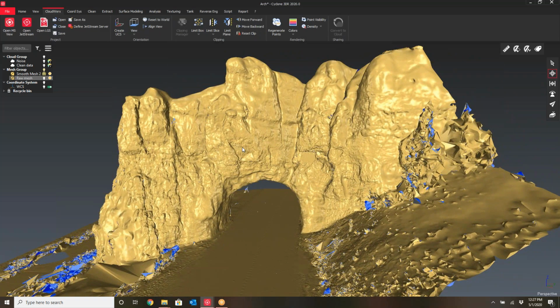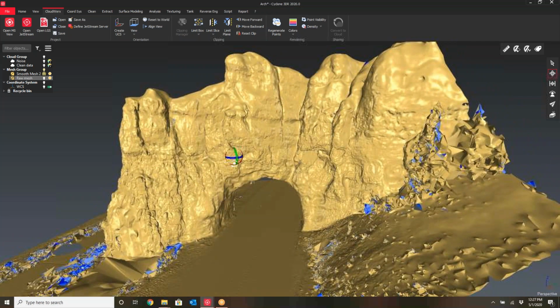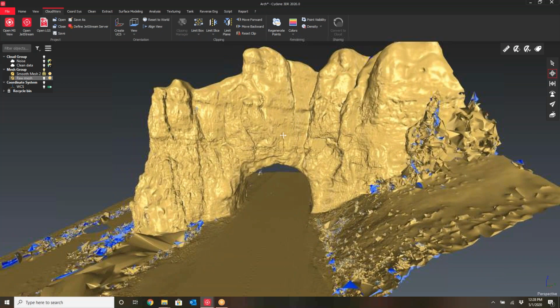We created a surface out of this, and then we didn't use an MS60, even though we could have. But the inspect surface app, or just to do like an elevation, just points deviation from the surface. And so if you had a few targets set up, great. But yeah, with the inspect surface app within any of the multi-stations, take this surface out, scan it twice a year, and you'll get deviation reports right there in the field. So, yep.